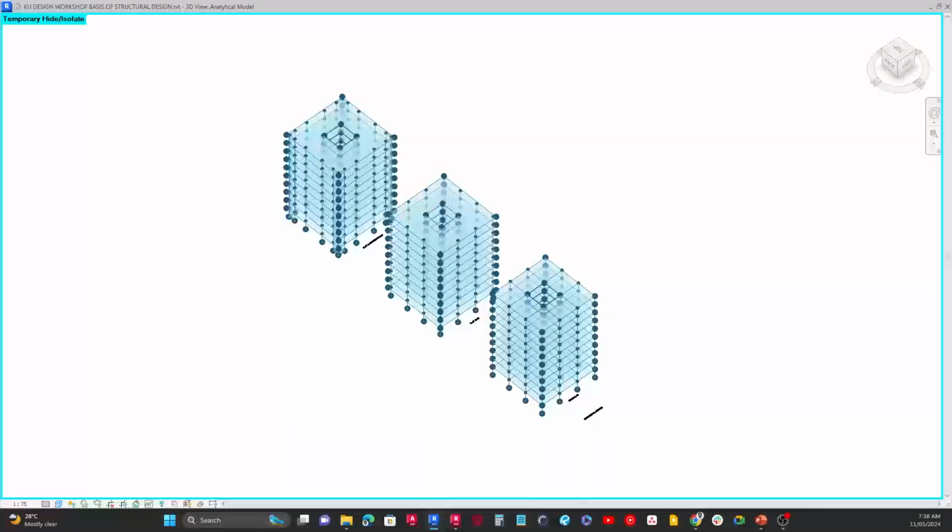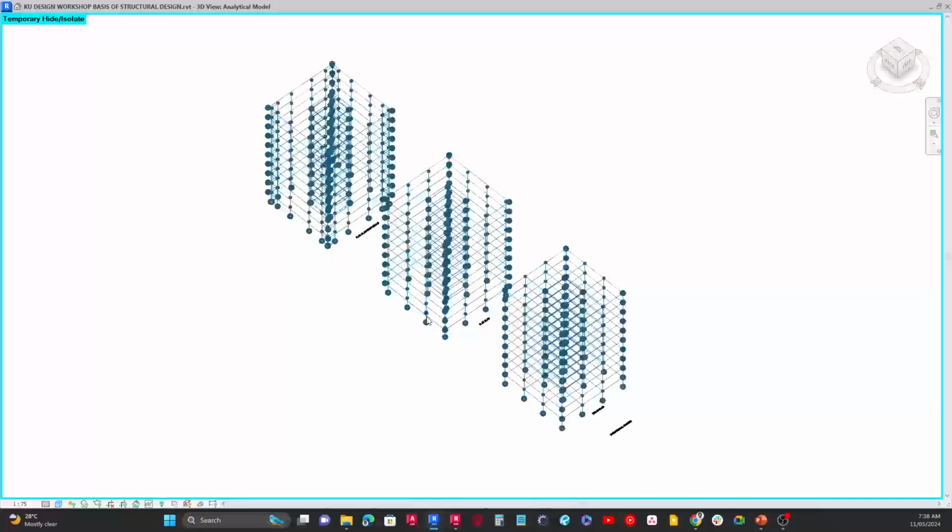You understand? So that's after the concrete has probably cured for maybe 28 days or more, and you know the actual strength when you test it in the lab. But C pertains to design, right? So we are not mixing anything. As designers, we need to have standards for the type of concrete grade. So basically they're the same thing, they just mean different things depending on the scenario. Okay, I hope that was able to answer your question.